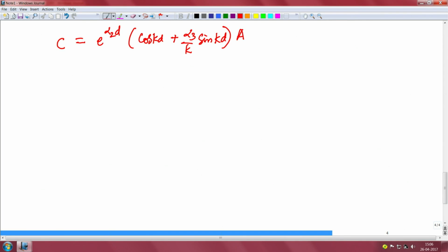We are not concerned with the actual value of a, so we will not try to evaluate right now. And in fact, when we are computing the mode fields etc., we can normalize it saying that the power is equal to 1 and evaluate a. So, we can use the fourth equation to evaluate the b rather than evaluate any other coefficient.